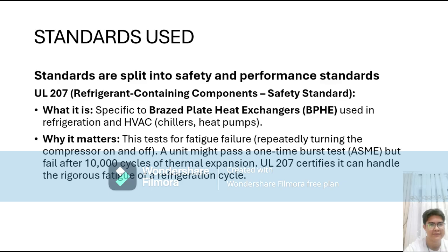A unit might pass a one-time burst test as per ASME standards, but it may fail after 10,000 cycles of thermal expansion. UL 207 certifies it can handle the rigorous fatigue of a refrigeration cycle.